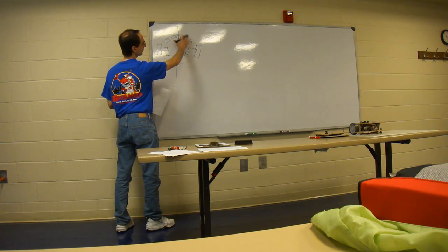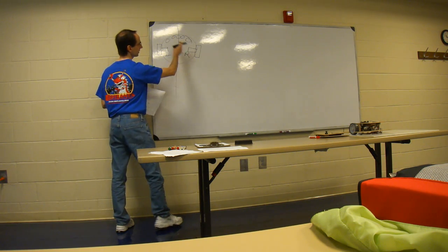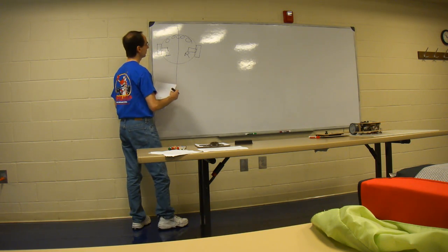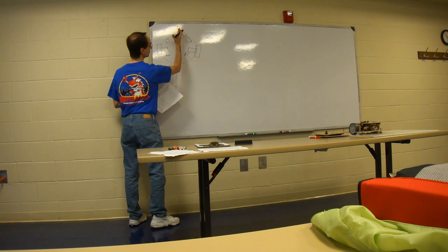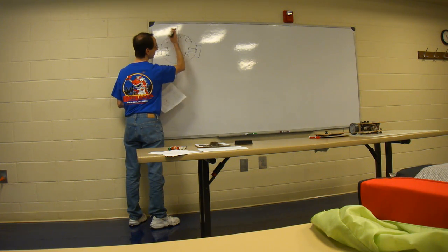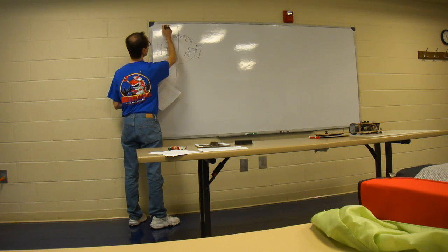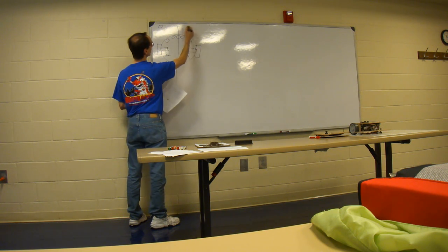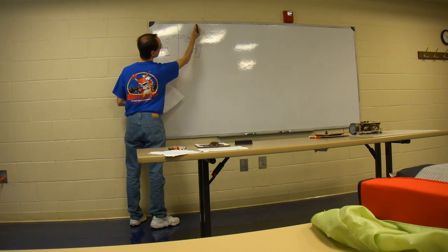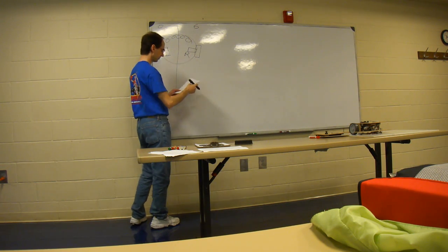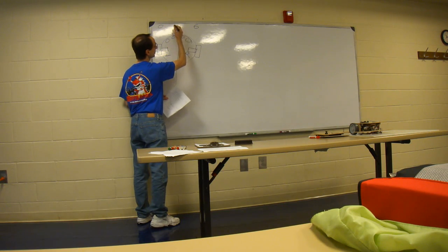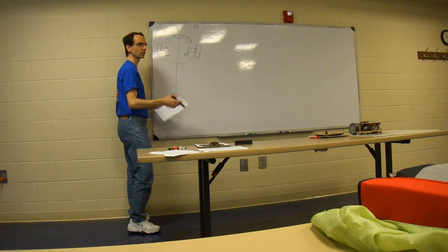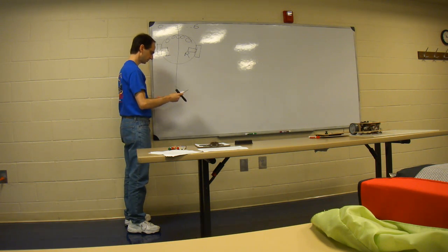And these sensors send a signal to your microcontroller, and it's going to give you a value as to where the line is. Let's just say this particular sensor, when the line is all the way over here, gives a 0, and when it's all the way over here, it gives a 6. So in the middle, we're at 3, and it gives us all the points in between these two, or at least a lot of points in between.